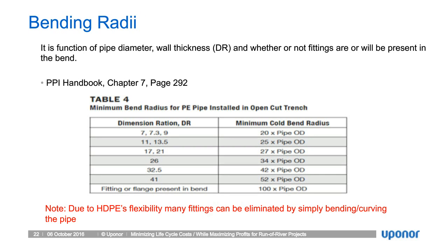The bending radii is another aspect because it is a flexible pipe in relationship to rigid pipe. By having that ability to bend the pipe to a certain radii, it allows us to eliminate a lot of fittings and couplings, which, because of the transition or the lips, would each cause some loss of differential pressure within the pipe. So by having a continuous pipe, we minimize any pressure losses along that line, and again try to maximize the power output to the turbines.